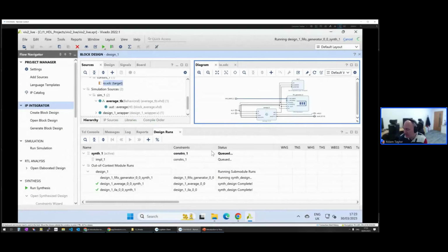So that's a great question. So an embedded register would mean, and I've closed the view now, an embedded register within the block RAM itself. So within the block RAM, and then there's a FIFO. A fabric register could also be implemented if you wanted. So you could put the register in the user register in the programmable logic, user register in the block RAM, or if you wanted sort of belt and braces, you could use both.